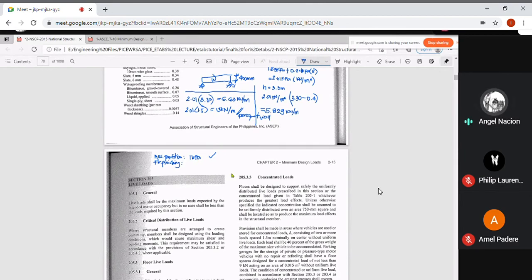And then you should also have your ceiling. When we say ceiling, that includes the mechanical ducting and the like. Okay? Ceiling. So all in all, this usually ranges around 2.5 normally, 2.5 kilonewton per square meter. Okay? So you will put values here depending on the section that the architect will give, which you will see later on in your design.